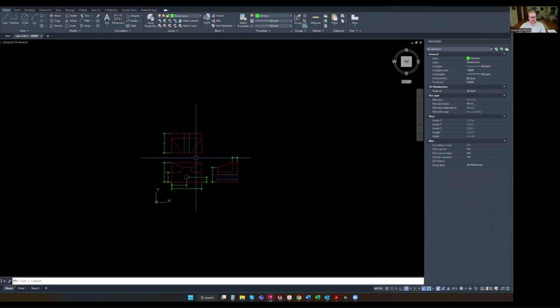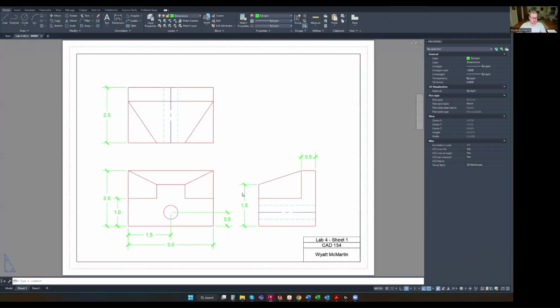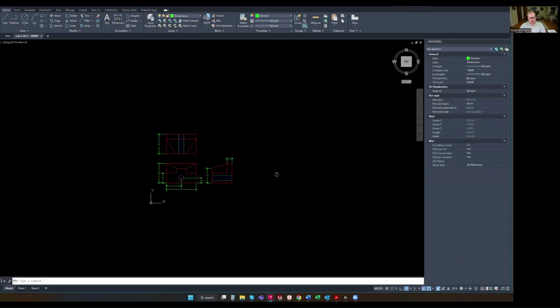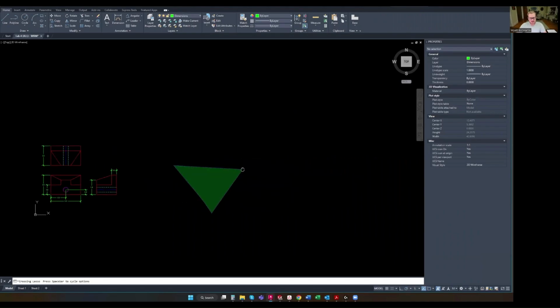So now, one of the last things we did in the Sheet 1 video was delete our 8.5 by 11 rectangle that we used to position in the previous labs so that we could always draw where the viewport was. So this time, we don't have that reference and we're not using the grid. So in this case, let's go ahead and just create another rectangle here. I'm going to use my rectangle tool, which you can find up in the Draw toolbar.